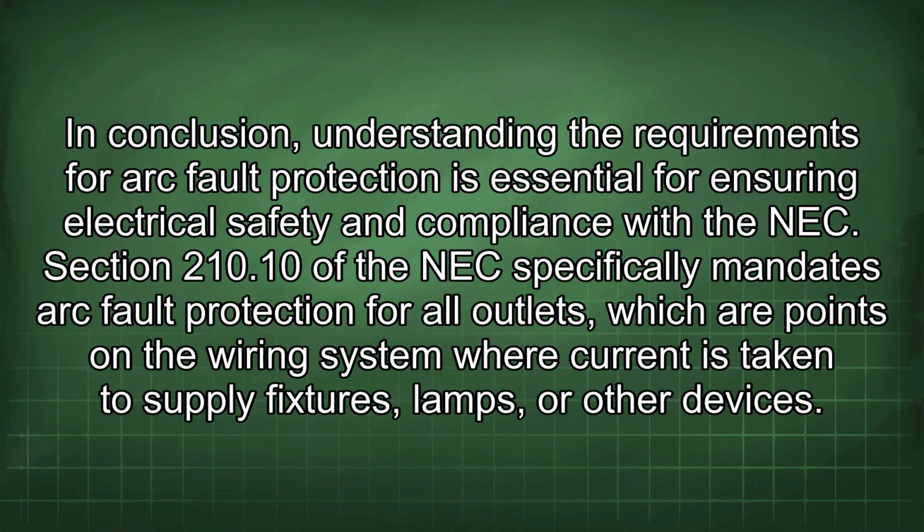In conclusion, understanding the requirements for arc fault protection is essential for ensuring electrical safety and compliance with the NEC. Section 210.10 of the NEC specifically mandates arc fault protection for all outlets, which are points on the wiring system where current is taken to supply fixtures, lamps, or other devices.